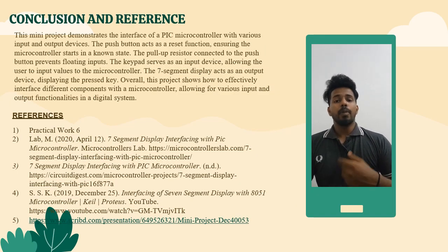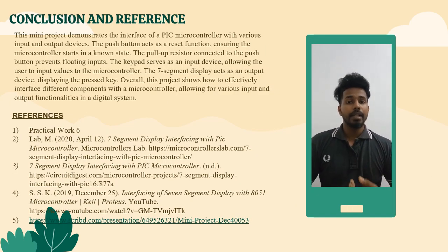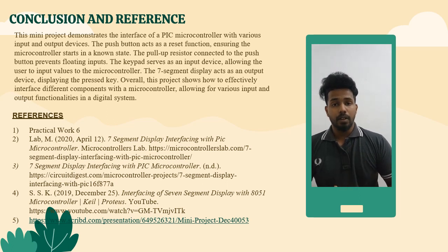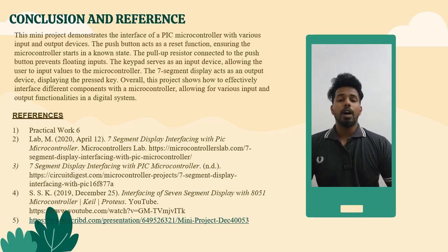In conclusion, our project exemplifies the seamless integration of a PIC microcontroller with various input and output devices. The push button serves as a reliable reset function, ensuring the microcontroller starts in a known state, while the pull-up resistor prevents floating input for stable operation. By introducing a keypad as an input interface, users can input values to the microcontroller, with the 7-segment display accurately reflecting the user input.